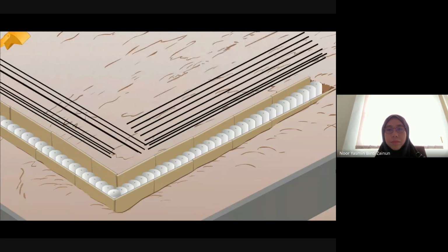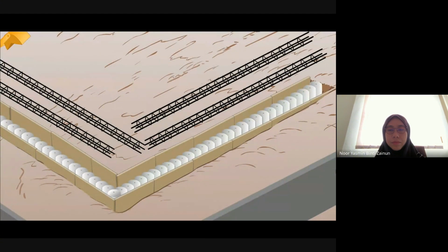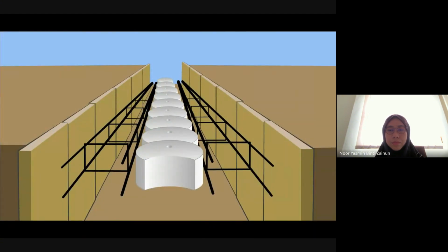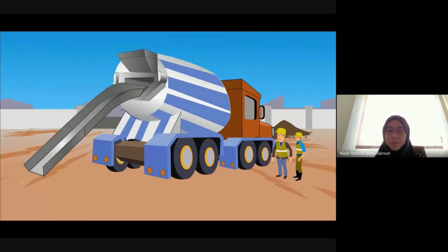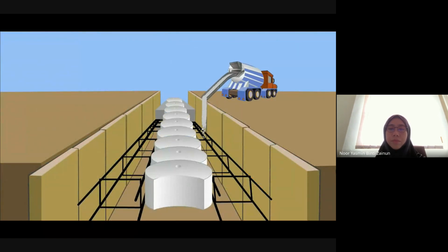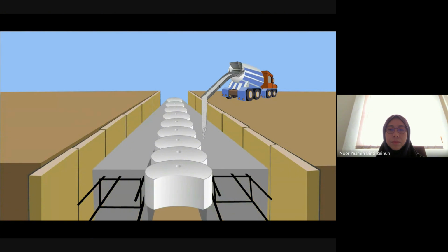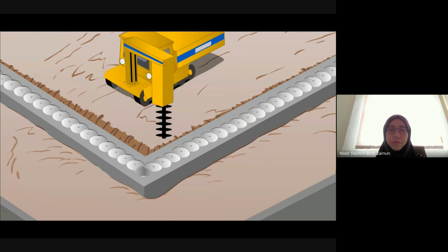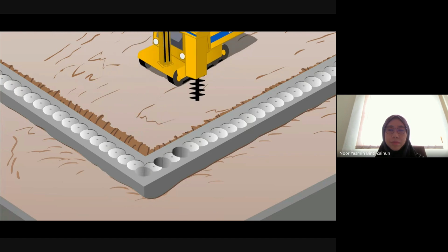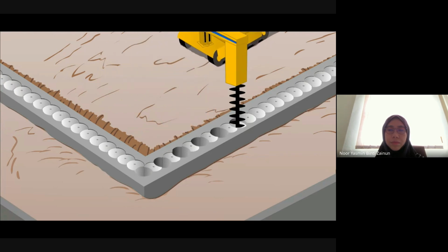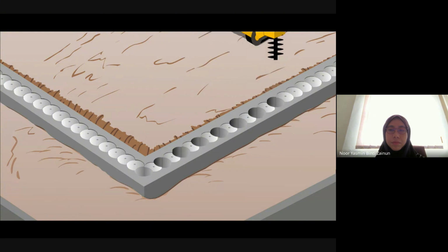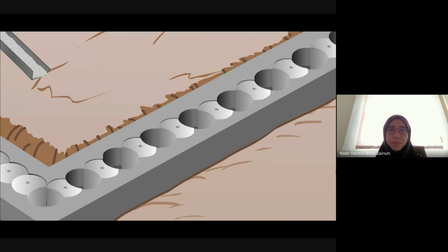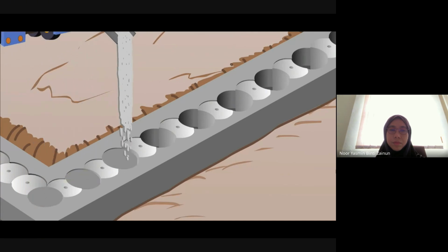The process starts with the construction of a shallow guide wall. The EPS forms are used to shape the inner curved face of the guide wall. With the reinforcement in place, concrete is poured around the forms to complete this stage. When the guide wall is strong enough, the primary or female piles are constructed. The piling rig drills straight through the forms to achieve accurate placement. The primary piles are drilled out with alternate spacing to form the intersecting design required for a secant wall. The piles are then filled with the first of 2 different concrete mixes.